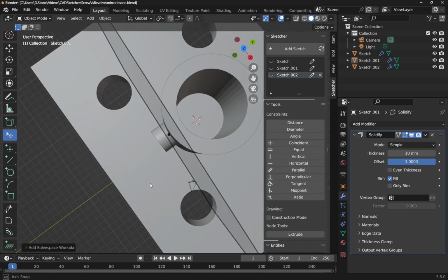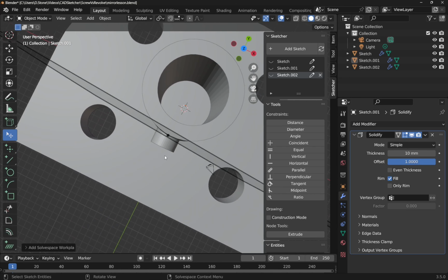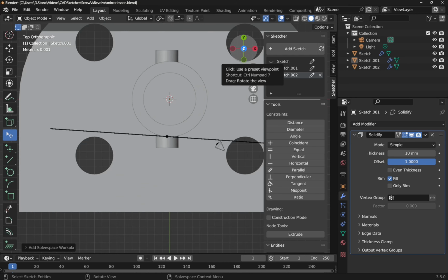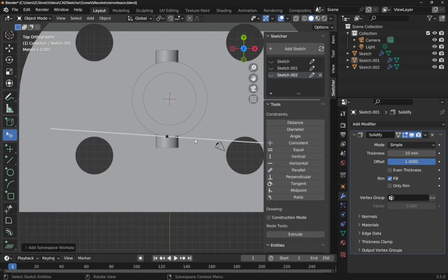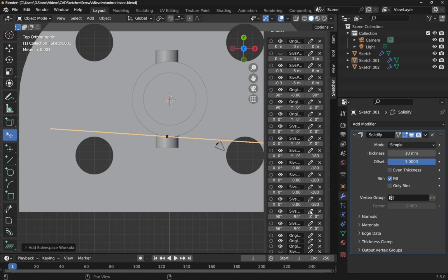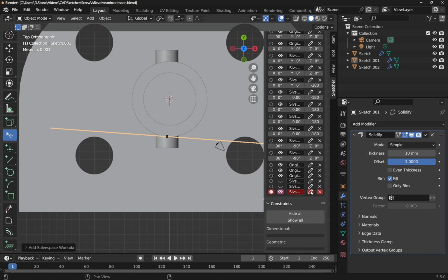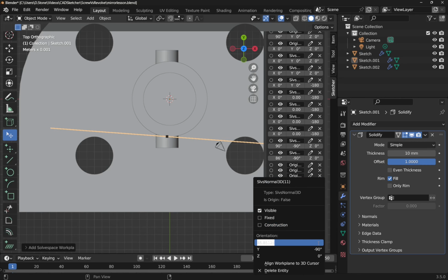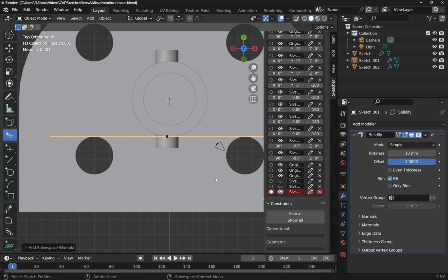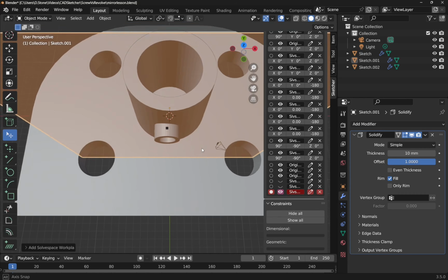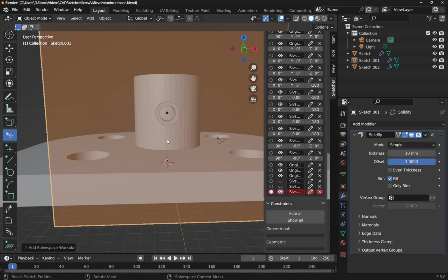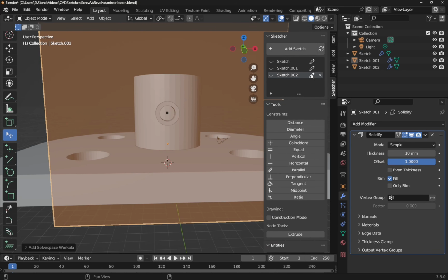So we've got the work plane sitting there, and that's nicely aligned with that face where it should be, but you can see it's at an angle here. So we do the same. We need to click on that plane and come down to the entities and find it in here. Double click and look at the X, and we need to set that X to 90. So it's nice laying flat upon that face there, and I can now add the sketch to that face.